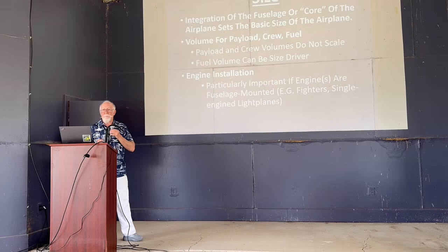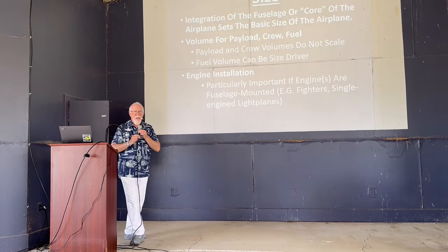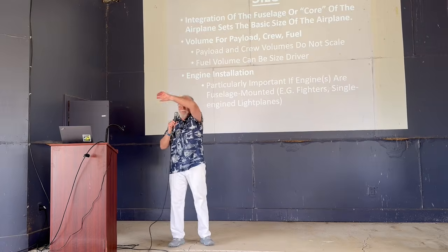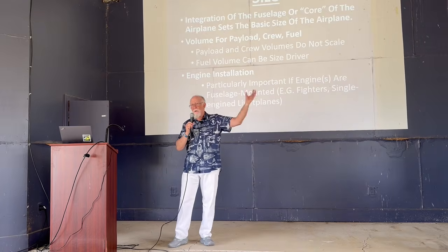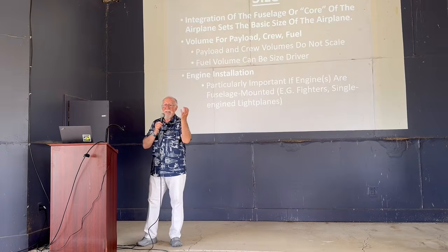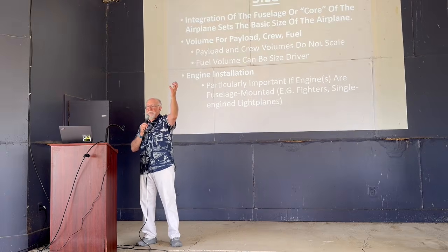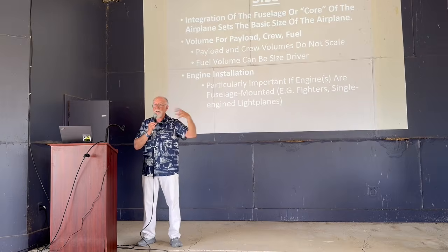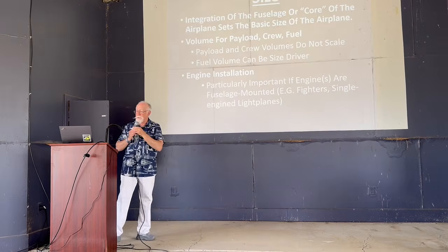Engine installations can bite you big time. You know, if you're just slapping the engine on the front of a tractor fuselage, not bad. If you're doing a stealthy jet where the air has to go through tunnels through the engines in and out, the weight of all of that ductwork turns out to be dramatic, and it can actually affect the optimum size of the engine. You know, the engine that you would pick in isolation as the optimum isn't the optimum when it's integrated because of what all of the installation issues are.